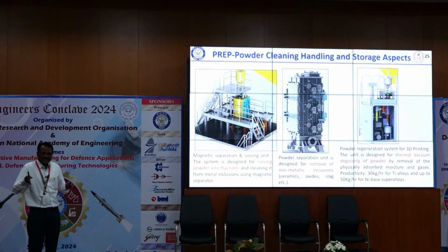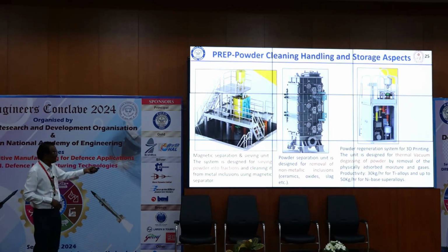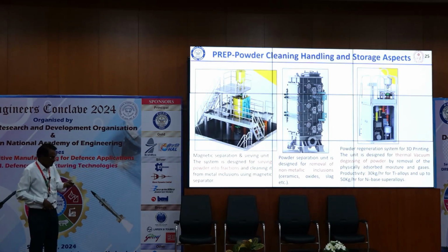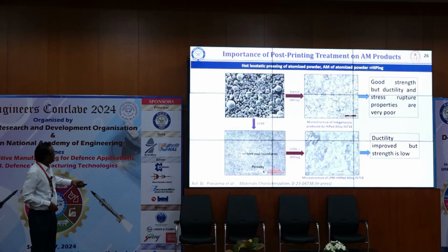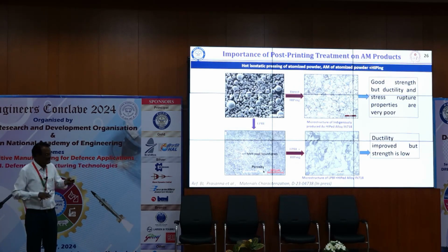Then powder cleanliness. If fatigue cracks initiate from the inclusions, then how to avoid them, by sieving, and how to remove the metallic and non-metallic inclusions with the equipment available today. And another thing, finally, this is the final slide.